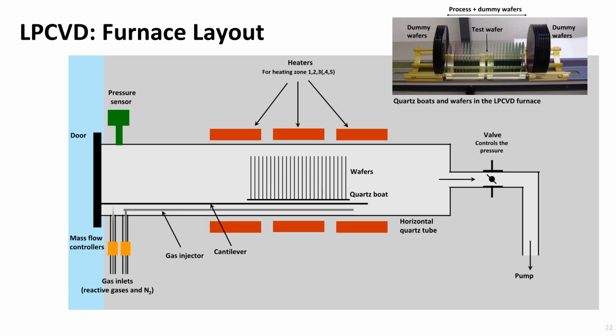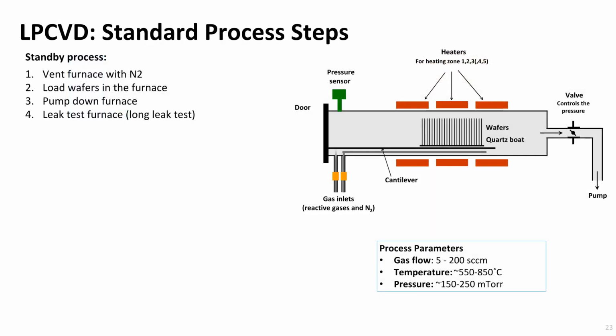One exception is the E-stack where quartz with dummy wafers are always present and quartz boats for substrate wafers are placed in between. This will be explained in detail during the training session. Even though the process itself is relatively simple, the practical implementation is a bit more complicated than the oxidation process, mostly due to the presence of toxic and flammable gases in combination with high temperature during the deposition process.